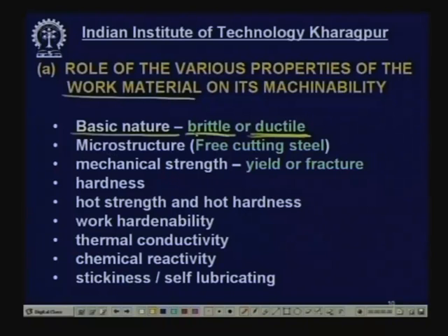So, brittle materials are easier to machine, ductile materials are also easy, but if too ductile or too soft may be problematic. Now, the microstructure, as I already told: if it is a coarse microstructure, then the machining will be easy. If it is a discontinuous structure, then because of stress concentration there will be brittle fracture, because toughness will fall, and machining will be easy.